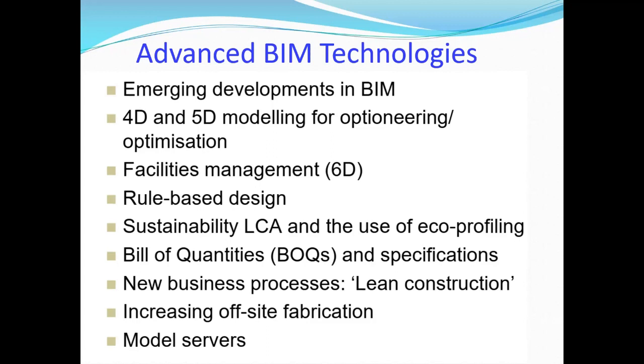Sometimes you say reduce the quantity, but it may not be value for money. Because if you reduce the quantity, your construction method may be costly, and it may take a long time. So how to do this analysis? Then this model comes into play. Before reducing the member sizes, you know the quantities. You can calculate how much formwork area and so on. After reducing the quantity, you can calculate the formwork area and quantities again. Then you can do the comparison.